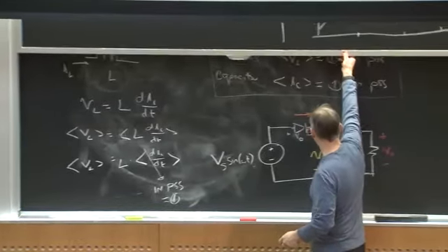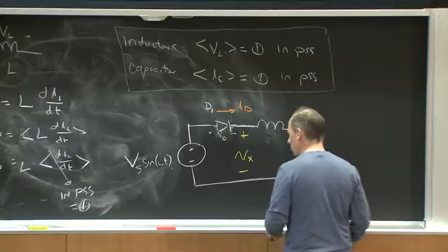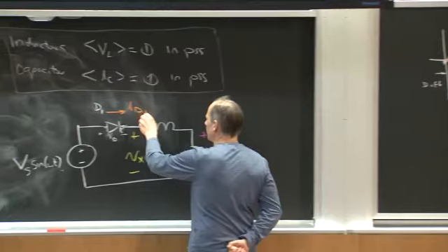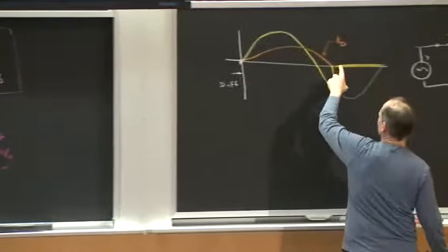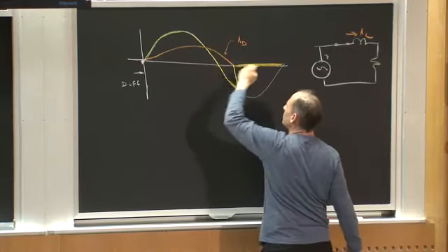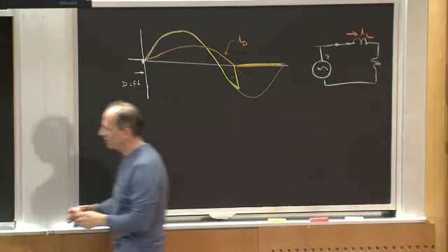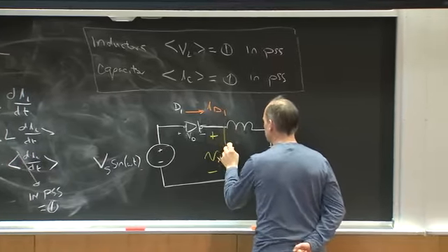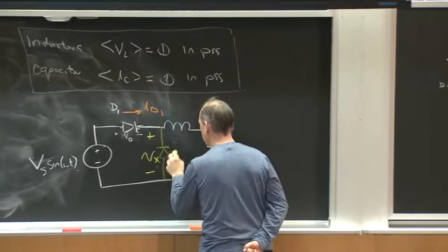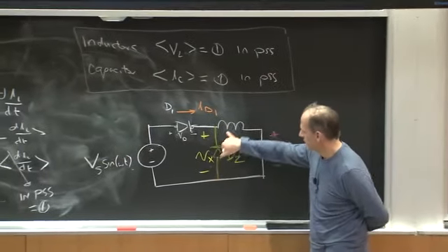Okay? I will build this, but instead of just having D, let me call this D1, and I'll call this ID1, right? My problem is that Vx is going negative. And then that means that, instead of getting this positive bump and then 0, I'm getting this negative part because the inductor current's holding the diode on. Well, maybe I can just get clever, come in and add a second diode here, D2. Okay? This diode D2 can take the inductor current.